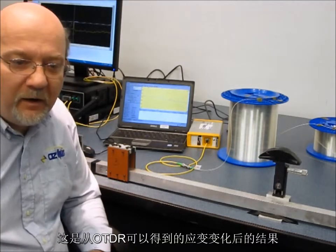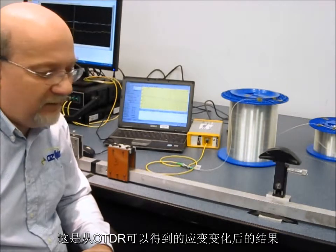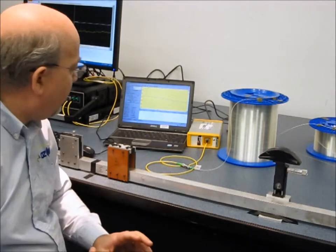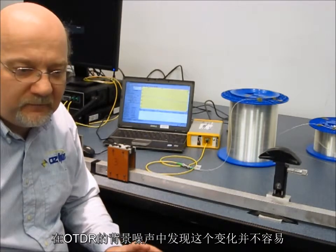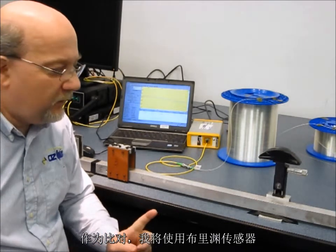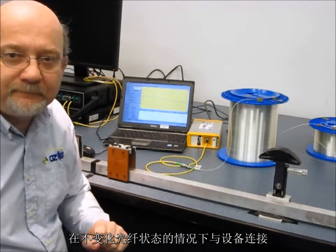So these are the signals and changes that you have to pick up with an OTDR in order to detect the strain on the fiber. And as you can see, it's a very small change, and it's hard to pick those changes out compared to the background noise within the OTDR signal. Now for comparison, let's hook up the fiber to our Brillouin sensor and make the same readings without disturbing the fiber.